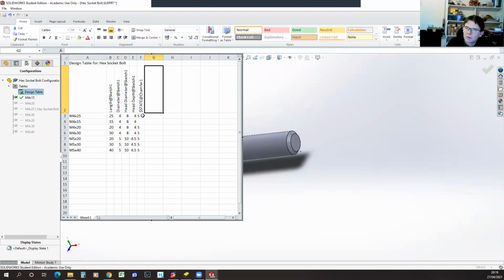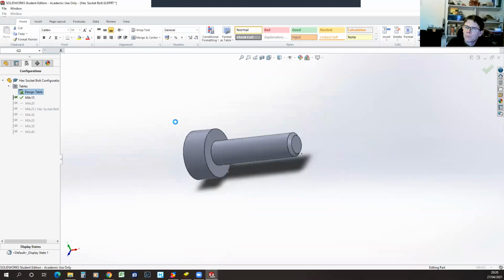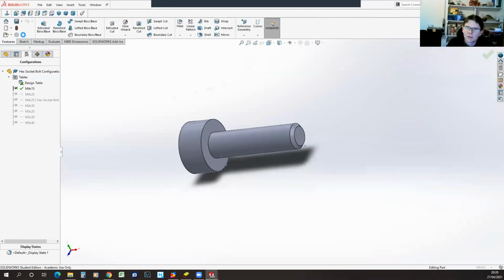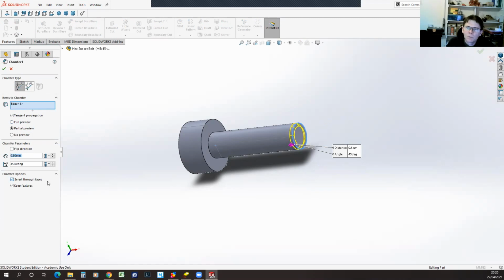it's added, interestingly, it's added chamfer state and not the chamfer dimension. Not quite sure why it's done that. And it's not going to let me undo it. I think chamfer state, because I think when I added that chamfer, let's go back to the, it is applied to all configurations.